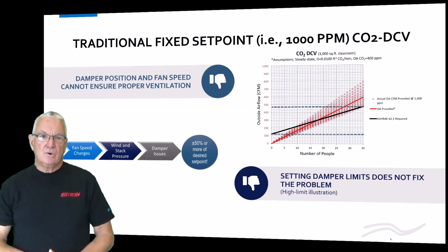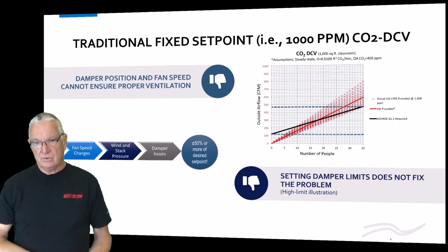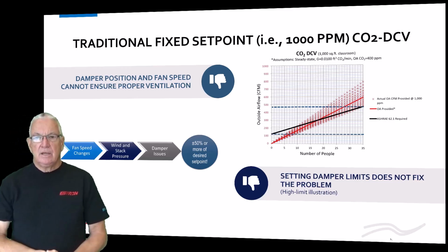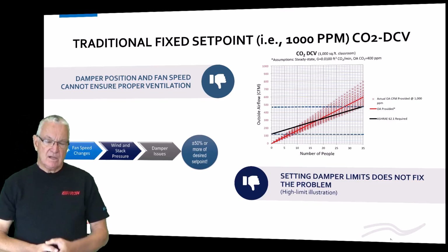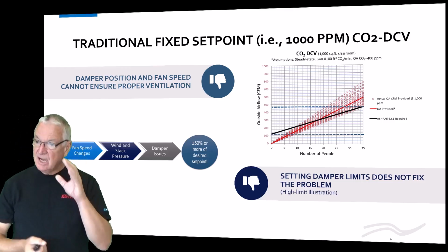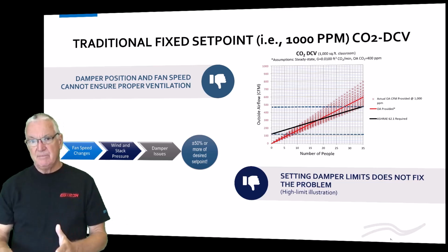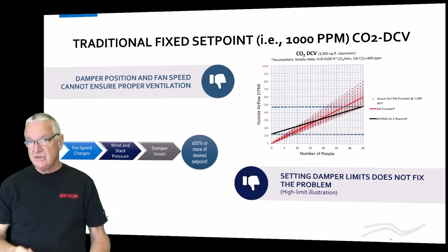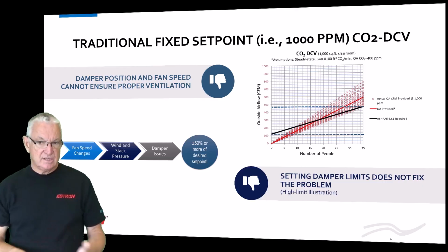All right, so what might you do, okay? What you might do is say, well, I don't allow this to happen because I have a min-min and a min-max damper that I use for limit control. I either control at those 2 points or I use them for limit control.